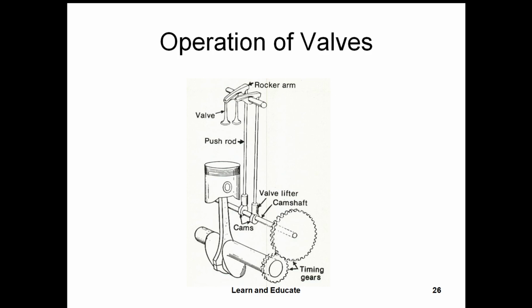So valves will be operated using a rocker arm and a camshaft mechanism, as shown in here. You can see here. So only during the intake and exhaust stroke, the valve should be opened, right? So during the intake stroke, inlet valve, and during the exhaust stroke, the exhaust valve need to be opened. During the other strokes, the valves should remain closed. So that is controlled by a camshaft and a rocker arm.